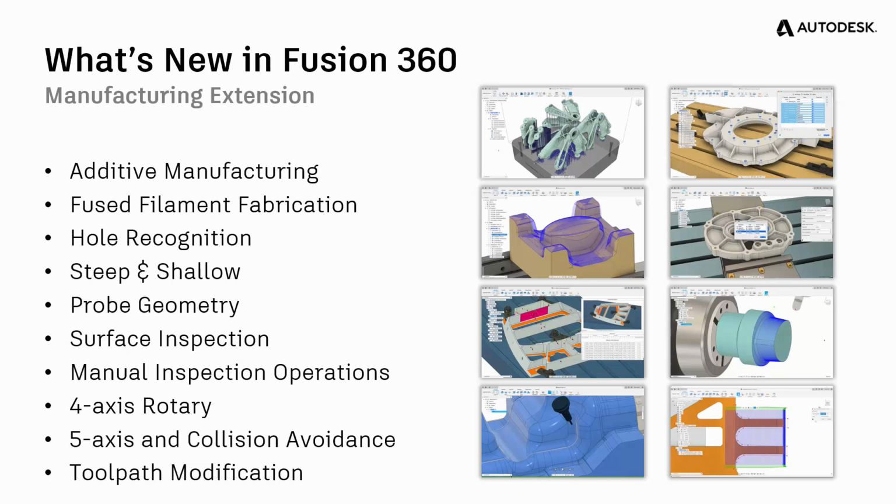We're about to include a new manual inspection operation, you'll see more of this later on, to allow you to define analog checks, so deburr checks, form of fit checks, dimensional checks that are not necessarily using a spindle mounted probe to measure the part.